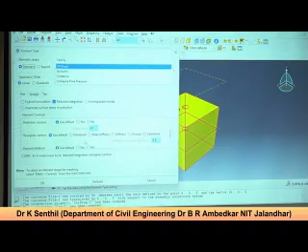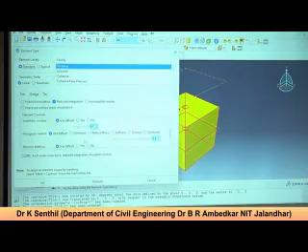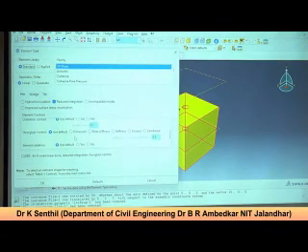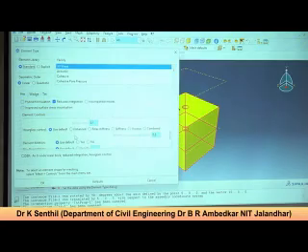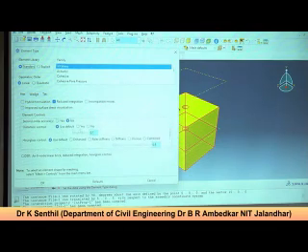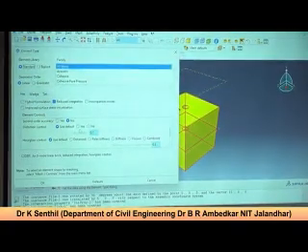So you have to take care of both whenever you do simulations. Now these are sufficient inputs, and then the element deletion options, of course. The dead element or the excessively stressed element is deleted automatically by default. The system will delete it while running. And also the distortion control by adjusting the parameter, because you have to calibrate, maybe a few trials you have to do with the coarser mesh, and then you have to go into converged or refined meshing.